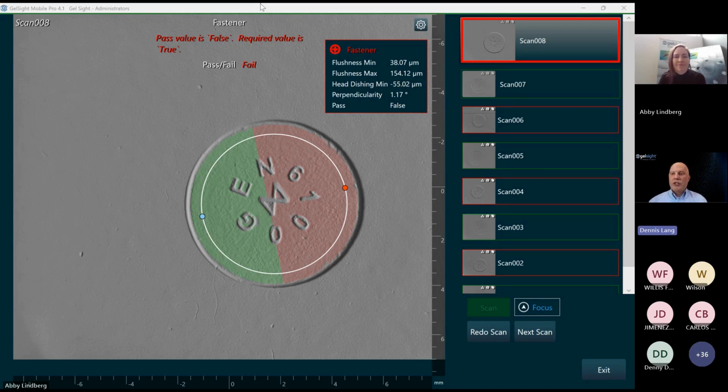When you look at a fastener flushness, of course, determining where you are on the surface, in some cases, the tool sets, it's extremely dependent on where you set it. GelSight uses the whole surface and creates the normal plane. Once some of these things were starting to be noticed in the lab, it really started to deliver what others couldn't, and people really started to appreciate that. So we're showing burrs, scratches, sealant gaps, micron level mismatches in the fastener holes, around the heads, even on the fasteners themselves. We can measure them all with GelSight, combine them in the same report.